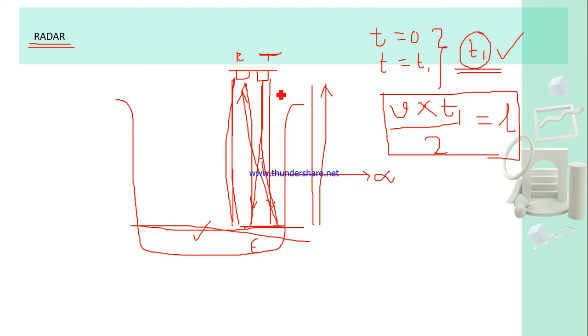So by using that, what will happen, the first case was non-contact type, but this will be contact type. So when this electromagnetic wave travels through this rod, and once the level is here, the impedance of propagation will vary based on the level of the liquid, and your time of flight will change accordingly, and you can also get the level measurement. Okay, so this is basically very simple. These are very simple techniques. This is the radar type level measurement.